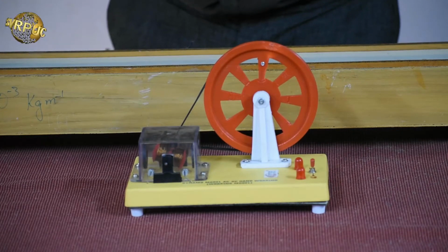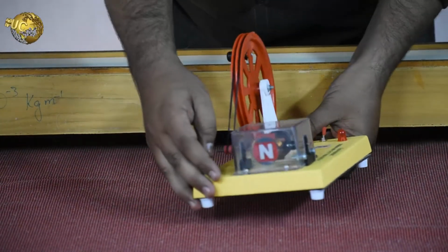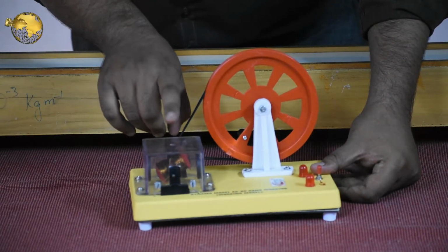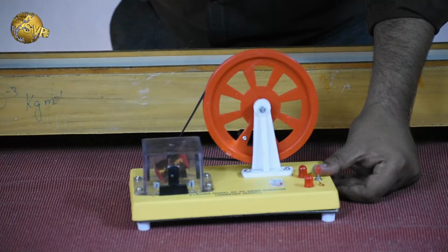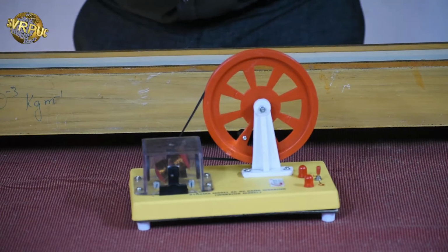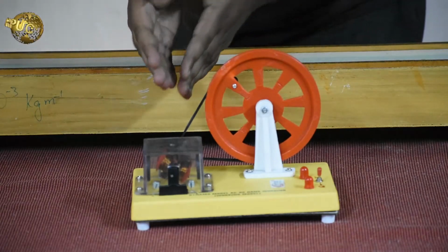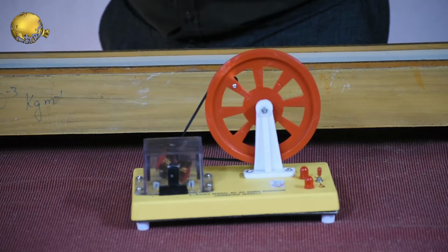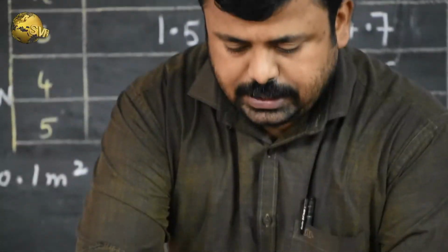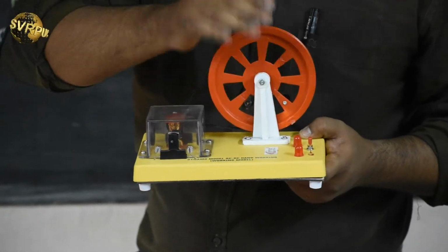Actually, this is what we get as the supply from the source. So here I have an AC generator, which converts the mechanical energy into electrical energy. And I move this. What actually happens here is the rectangular coil is kept between the magnetic field. When this rectangular coil moves, the current will be generated. Here this rectangular coil, when I rotate it, in a second it might give 10 rotations. So I can say the frequency is 10 rotations per second. The frequency will be the number of rotations per second. So if this rectangular coil rotates 50 rotations per second, I can say the frequency of this current generated is 50 hertz.